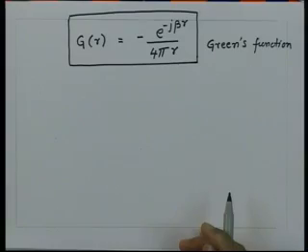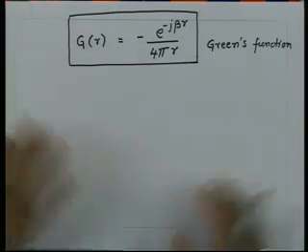Now, once we get the Green's function, or in a normal system, once we get the impulse response, which is what the Green's function is, the spatial impulse response, then the output of any system is the convolution of the impulse response with the driving function. In this case the driving function is nothing but the right hand side of the wave equation, which is minus mu times j.